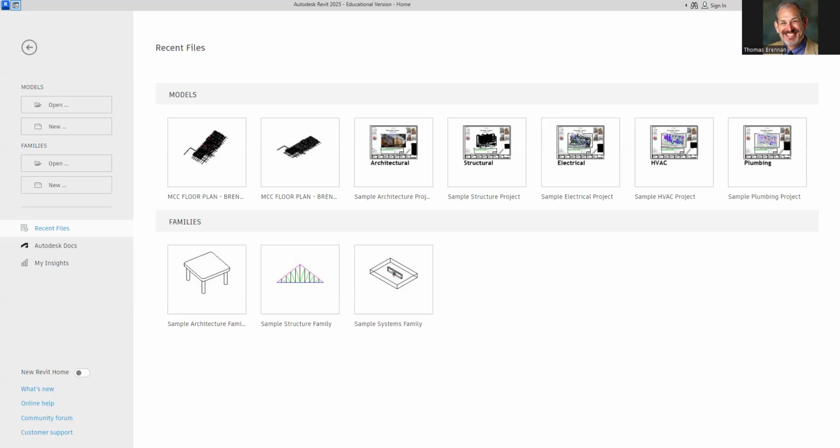There it is. All right, now at that point, double click on it. Make sure it's purple. Now what you want to do is add. Yep, so just add, you pick the walls, and then you need to get rid of the walls in between there. Yep, that's it. You got that submitted? Yeah. All set? Okay, good.